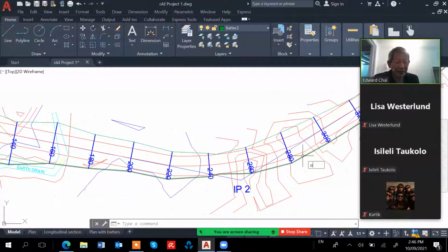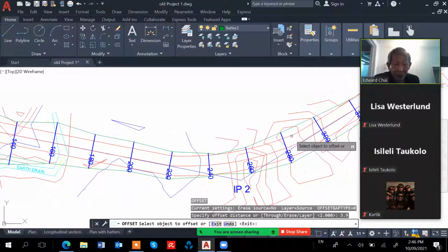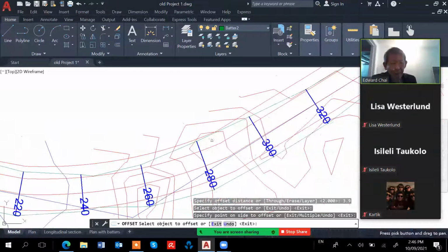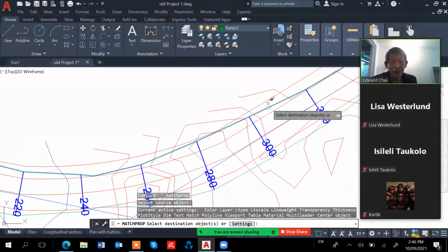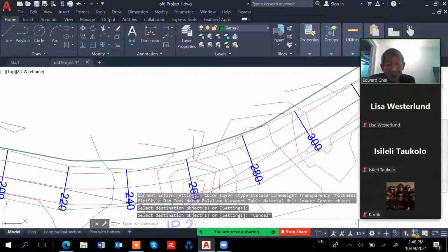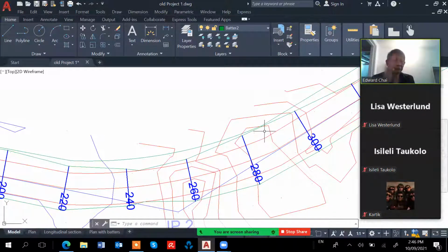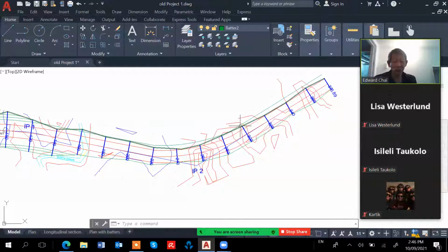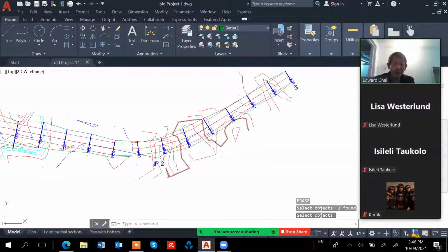So for example, you offset like 3.95 because for the cut it is 3.95. So there's no berm, because the cut slope hasn't reached 3.95. This one is probably near, so we don't need to have multiple slopes. Same thing on the right hand side as well.